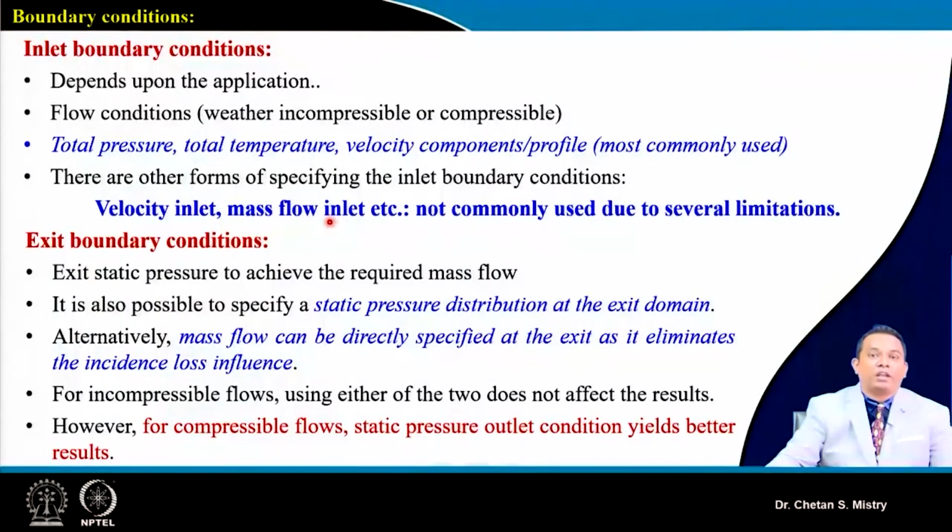Or suppose we have used a multi-hole probe to measure the inlet velocities before the rotor or stator. That velocity profile can also be taken as an inlet boundary condition. We will discuss this when I talk about the case study. At that time we will see the effect of taking those actual experimental results as well.